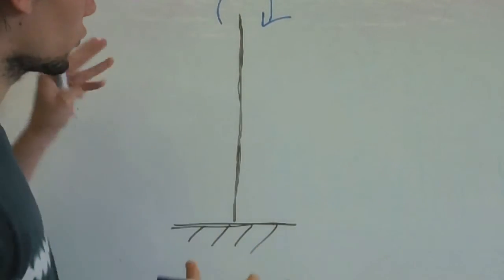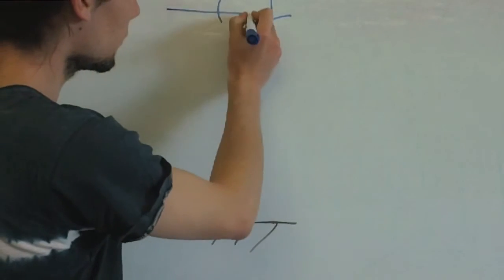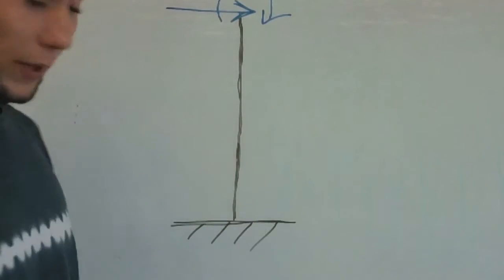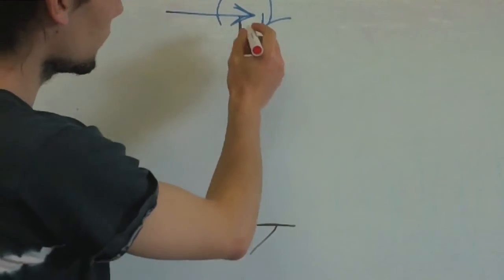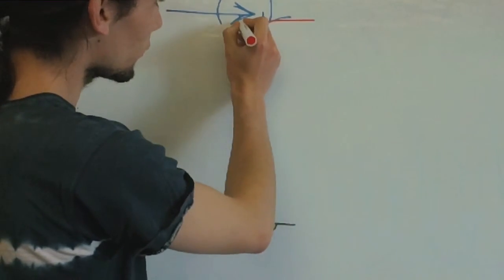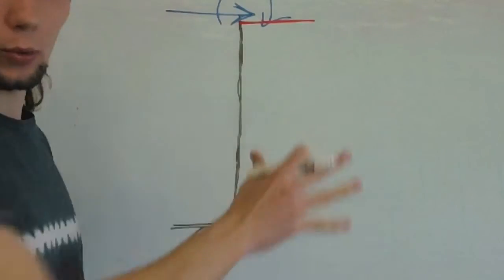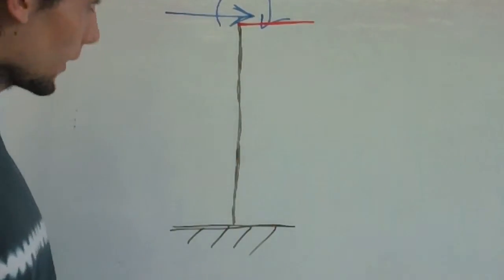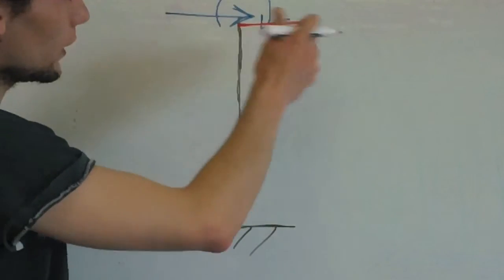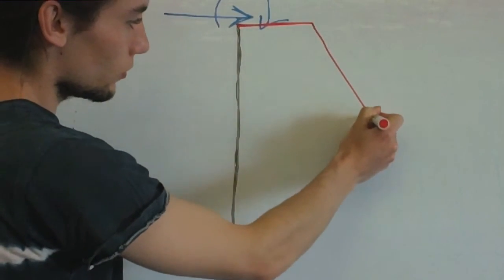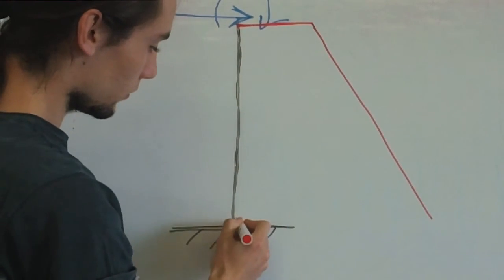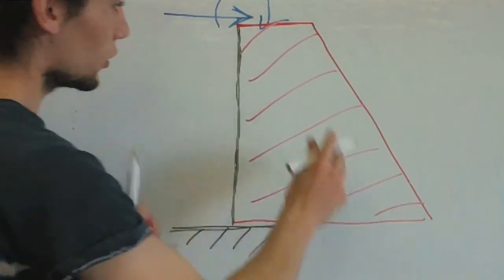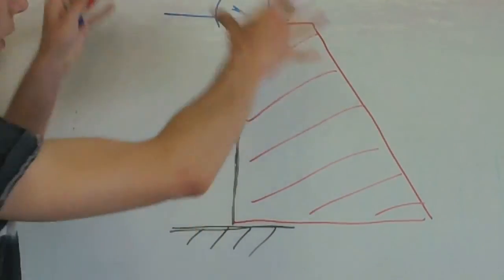and we've got a horizontal load which is going to be transferred over from the top of the structure onto this bit. So if we try and draw the bending moment diagram here, that concentrated moment is going to give you an original jump in the bending moment diagram. It's going to be equivalent to the sum of the previous 2 moments on either side, and together we'll get that. And then because we've got this load, the gradient is going to continue all the way down to the bottom. So there, we've almost got 2 different diagrams for 2 different parts of the structure. They come together as a whole.